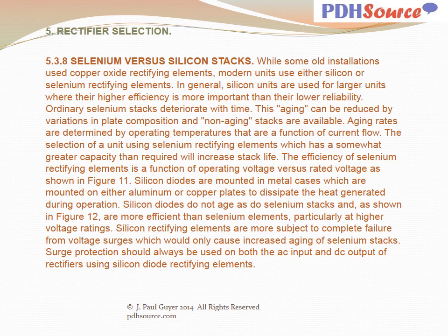Silicon rectifying elements are more subject to complete failure from voltage surges, which would only cause increased aging of selenium stacks. Surge protection should always be used on both the AC input and DC output of rectifiers using silicon diode rectifying elements.